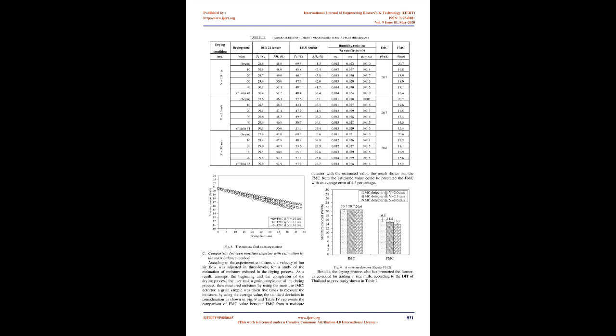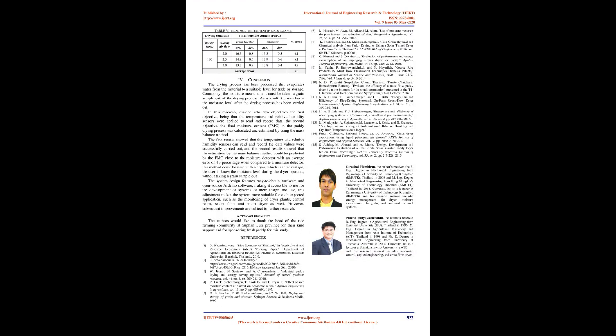The whole paddy grain consists of the dry paddy grain and the water inside the paddy. Lastly, prepare the data values from the drying condition and the experiment, such as the mass, MR, and the initial moisture content, IMC, of the paddy per one cycle of product, including the mass of water removed, MV, from the previous step. Then replace all of these values in Equation 6. The final moisture content, FMC, in the paddy drying process was estimated, and the FMC reduction during drying is shown in Fig 8.